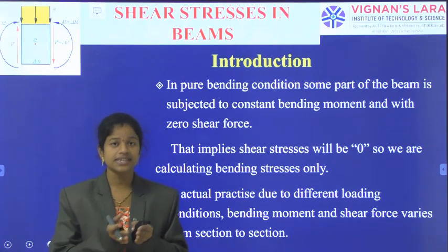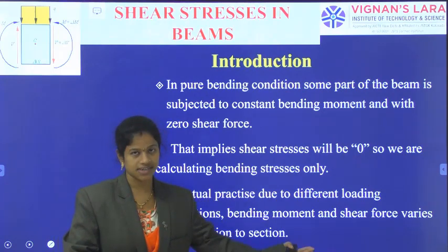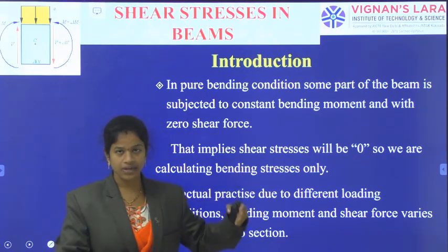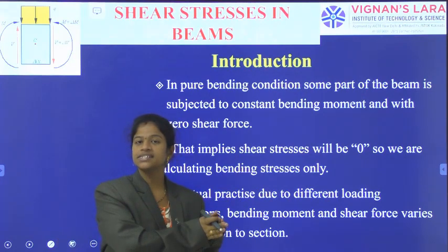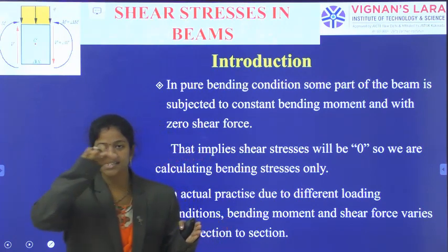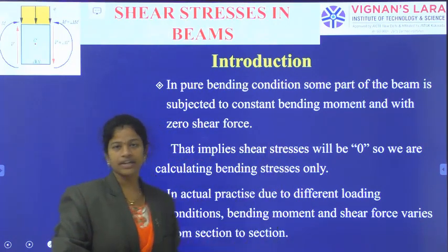As sections have different shear forces, they will have different shear stresses, and those shear stresses act along the transverse sections only. Due to the transverse sectional shear stresses, some complementary shear stress will act along the longitudinal layers. These points we have indicated.